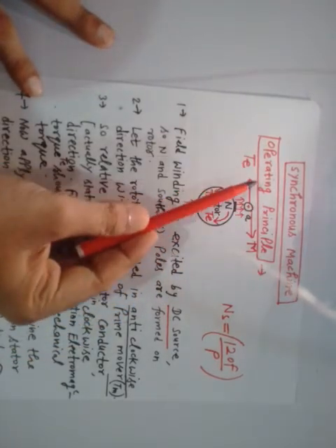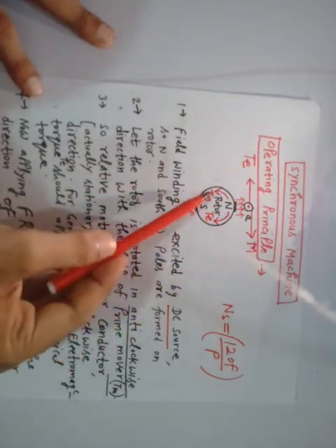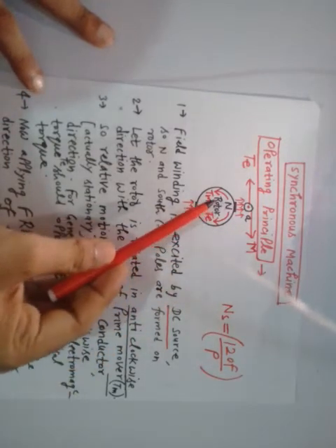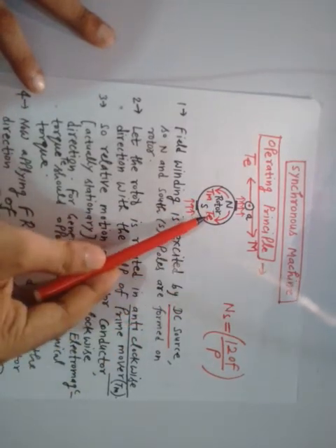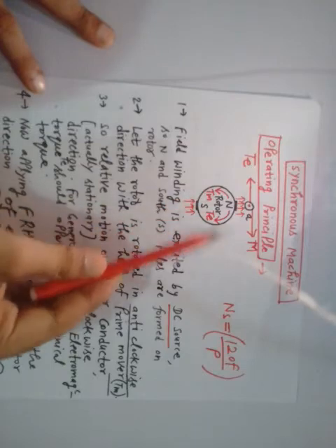And for energy conversion from mechanical to electrical in the case of a synchronous generator, this magnetic torque must oppose the mechanical torque. Then only is the energy conversion possible from mechanical to electrical. So this is the basics of generator operation. You understand now? So let us go further.